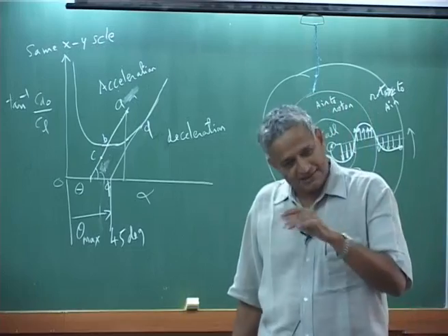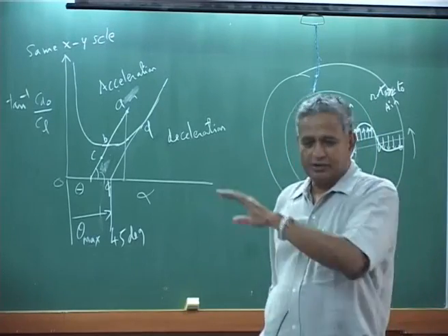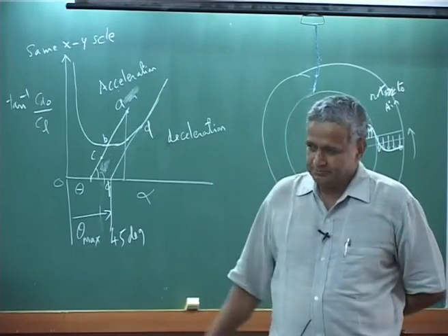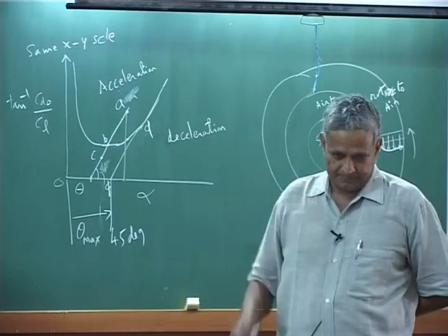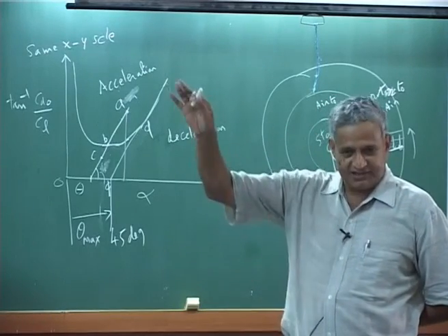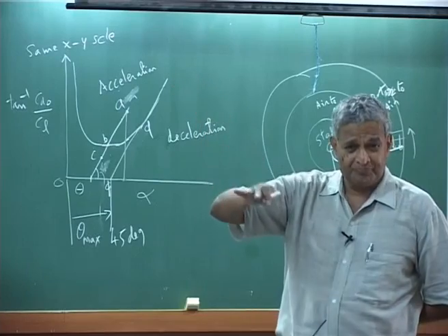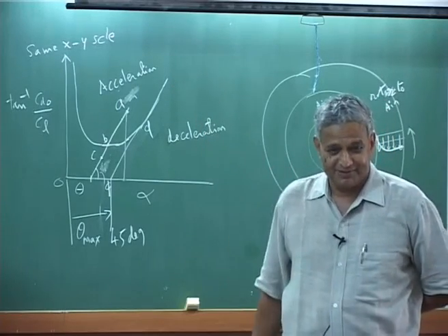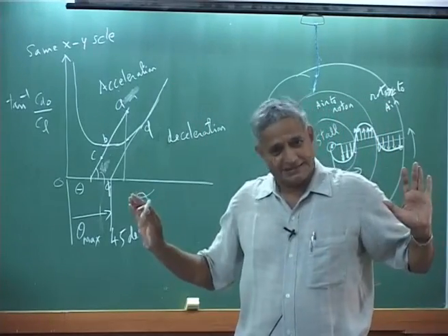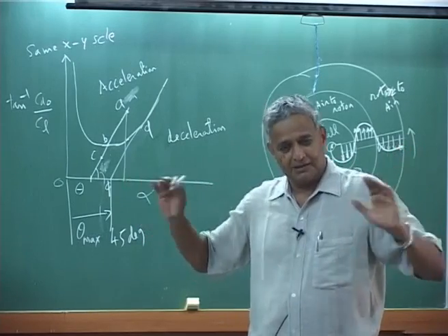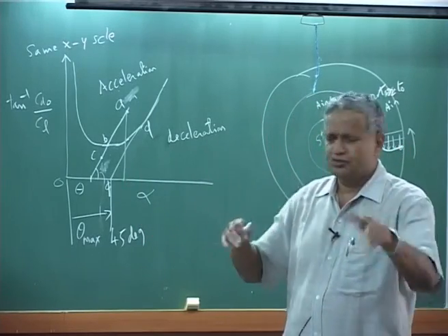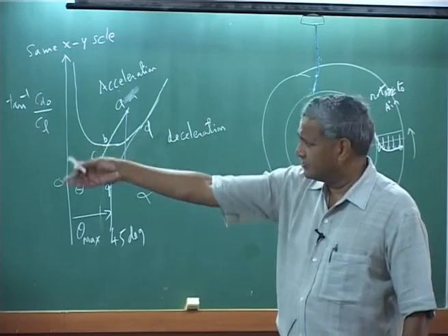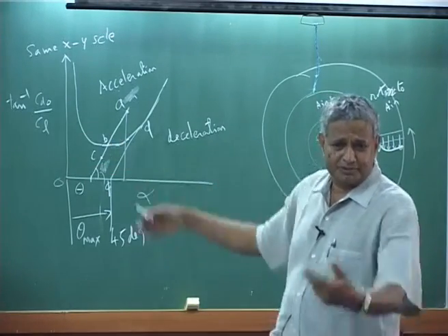That is why what industry will do for autorotation is, you have the code. You say power 0, the condition for which you keep on solving the problem for different descent velocities. You solve the trim of the helicopter, the entire problem, assuming some inflow velocity, because you have to take this curve approximation.